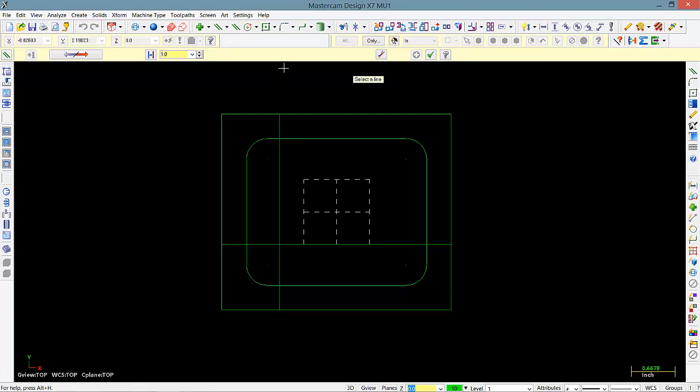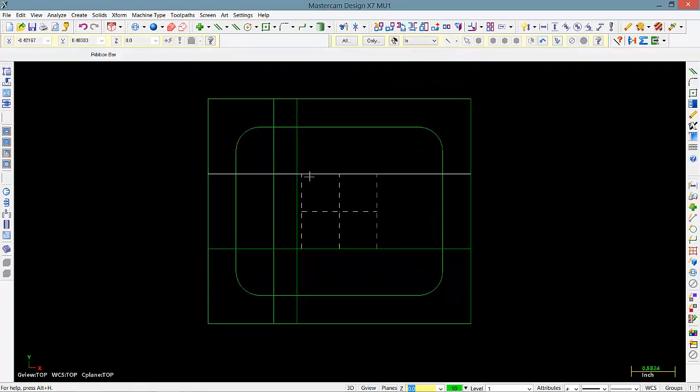So now this next one, I'm going to do an offset again. Grab this line, drag it out, and this one is 0.875 plus 0.3125. There we go, that looks good. I'm going to apply that. And then we got one from the top down that's also an inch. I'm going to apply that and hit the check because I'm done with lines. So here's our two center points, right here and right there.